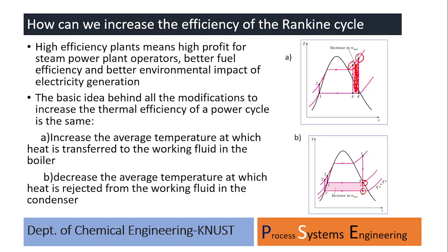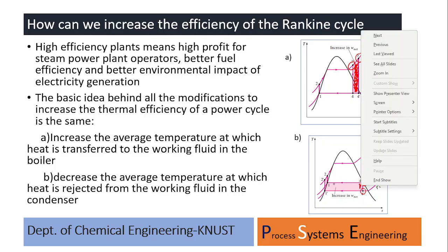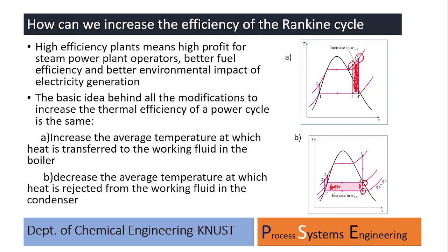So what that means is that the efficiency is also going to increase in relation to this magnitude over here. All we're just trying to say is if you have higher temperatures at point 3, for your superheated parts, you are going to be more efficient. And if you have lower temperatures after your turbine, you are going to be more efficient.